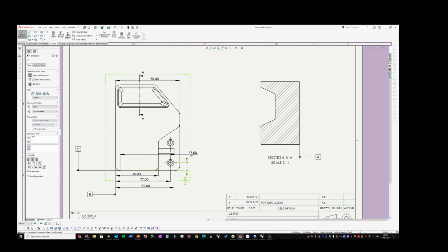So let's just do the start of this baby here. Okay, and I hope you're noticing that I'm going from smallest to largest, always from smallest to largest. So that's the smallest dimension, that's the second one. I'm not going to dimension that one because in fact that's a feature which I want that dimension there to be separate, and it relates to tolerances.